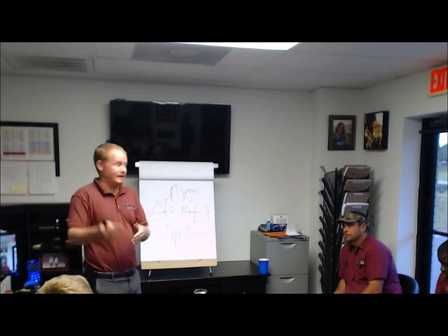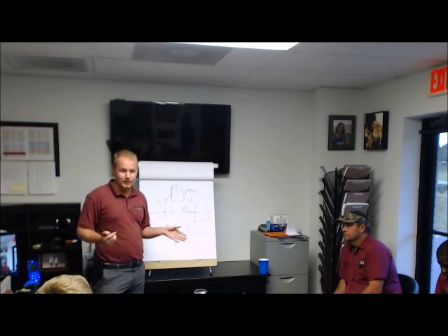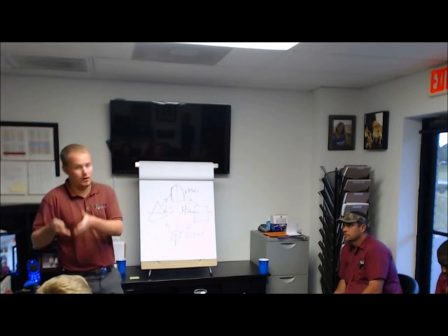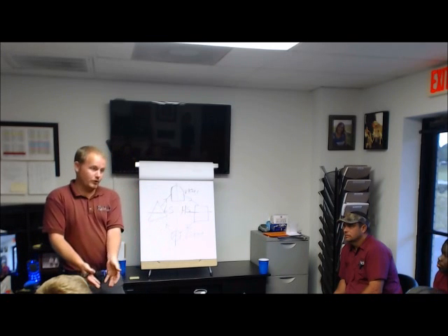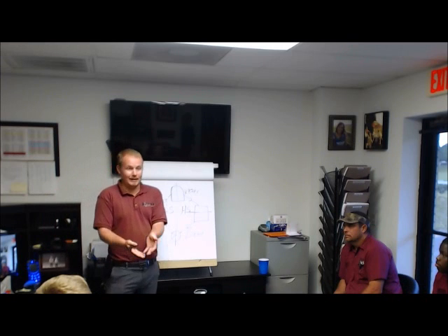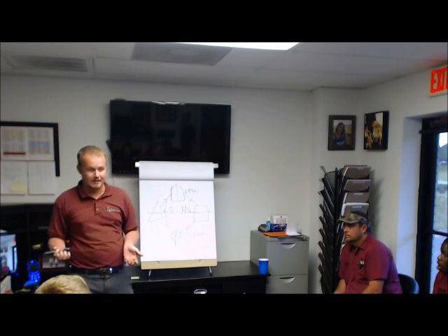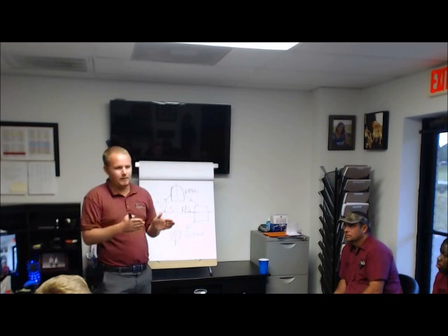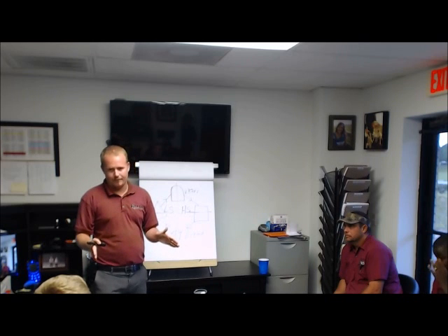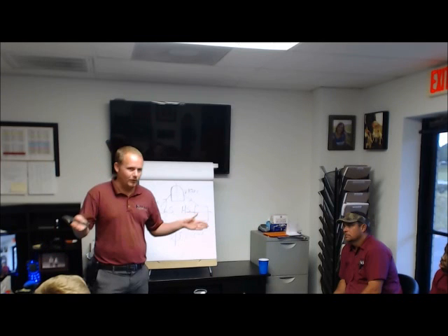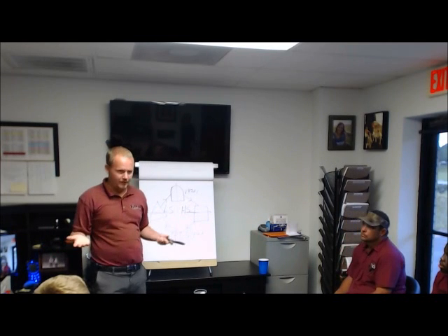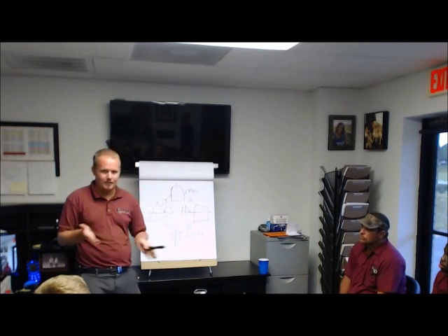Meaning, like what Leslie said, you're going to overfeed the evaporator coil potentially. You're going to run higher head pressure, which is going to cause your compressor to run higher amperage. If you undercharge the system, then you're going to have less refrigerant density. You run the risk of it freezing up. It has to have the amount of refrigerant that it's designed to have, and then it will be running ideally. But the problem is that we're dealing with systems that aren't brand new, and aren't perfect. So we're having to try to figure out that kind of happy medium.